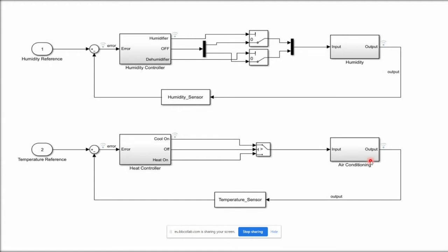Okay, so hello guys. My name is Musab. I will go into deeper technical stuff right now. So please focus here. We have two references. We're controlling the humidity and the temperature. Because as we said, it's the most efficient way of controlling temperature, to control the humidity with it. And at the same time, we want to balance a good, healthy humidity rate in the room.